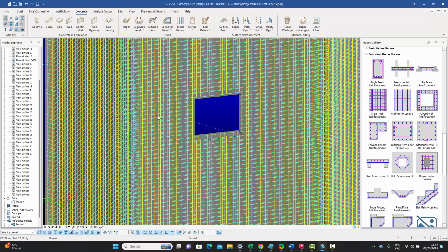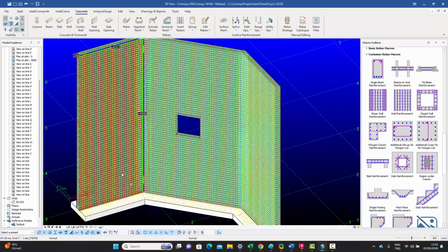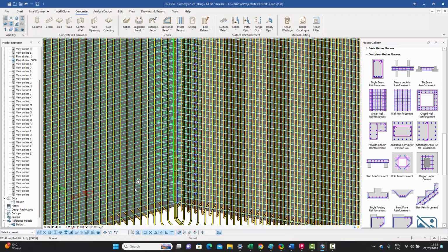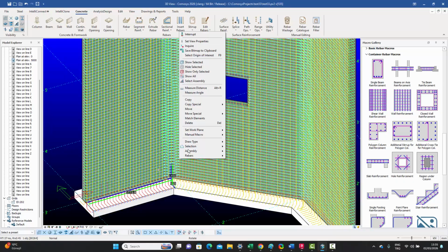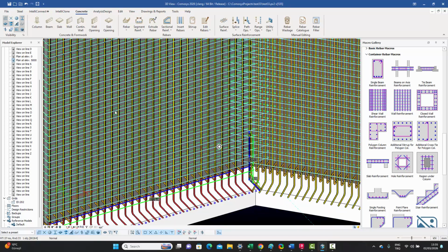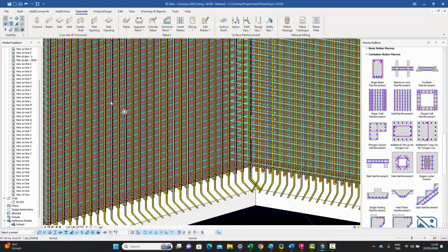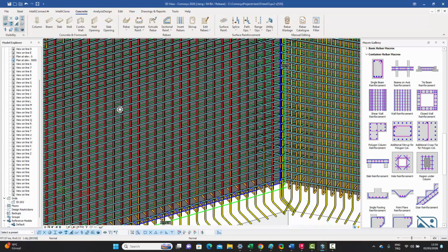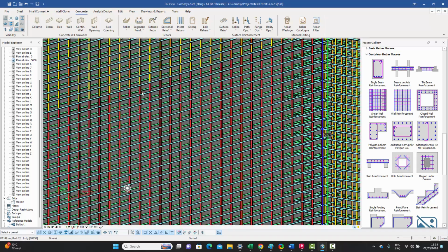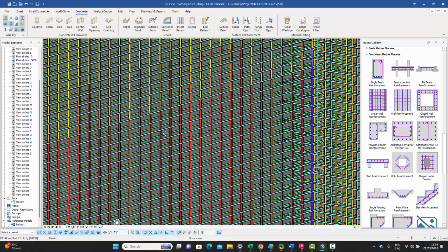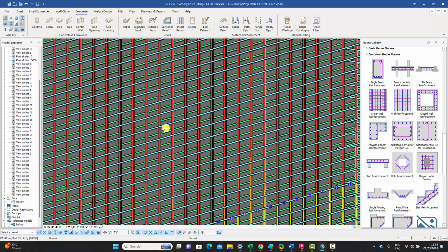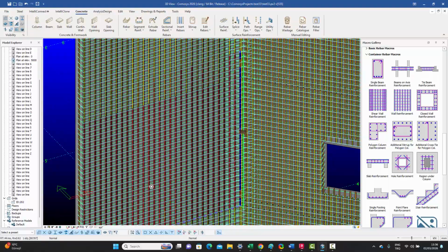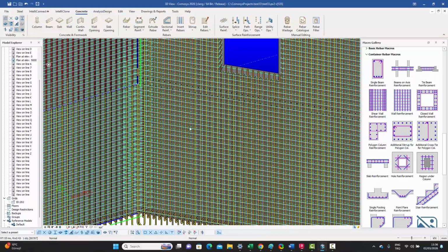And we also had the pouring information of splices. So let me select this bar. You can see that the starters are being selected. But if I select these ones, you can see that the pouring is at the 5 meter level, and then the next pour is at the 10 meter level, and the same holds for this side.